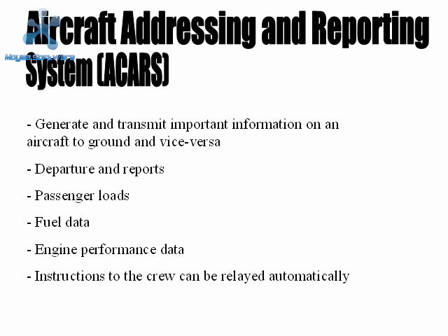ACARS, which is also known as the Aircraft Communications Addressing and Reporting System, is used to generate and transmit important information on an aircraft to the ground, or vice versa. It is a very high frequency digital radio transmission system. Some information that is transmitted includes departure and arrival reports, passenger loads, fuel data, engine performance data, and instructions to the crew.